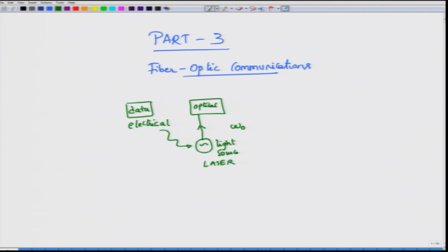So, what you actually have to do is to perform the process of modulation, wherein the carrier properties change. What are the carrier properties? The carrier properties will be amplitude, frequency, phase, and in the case of optical fiber communication, you also have an extended degree of freedom called polarization. We have seen that the LP01 mode can actually come in two different varieties, right. So, this is also an LP01 mode, this is also an LP01 mode. One is an X polarized mode and the other one is a Y polarized mode, and information on each of these modes can be independently modulated by changing the amplitude, frequency or phase.